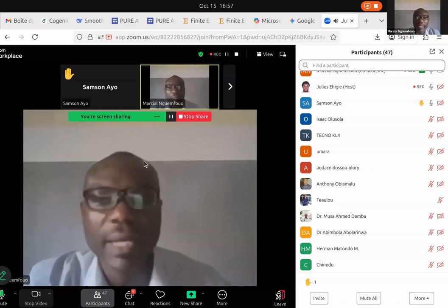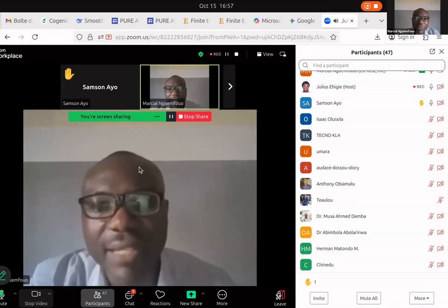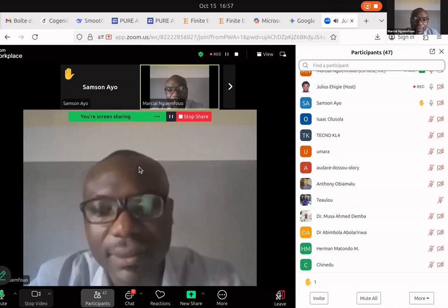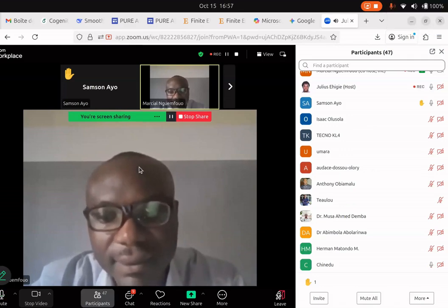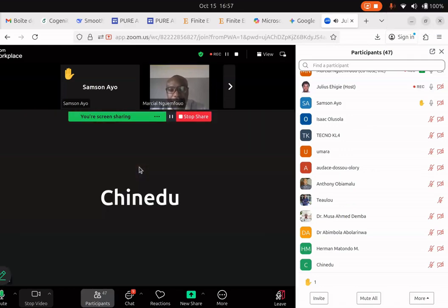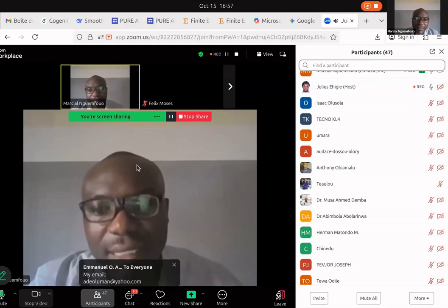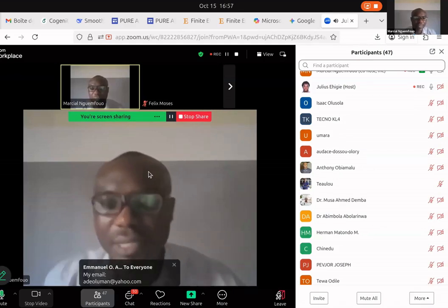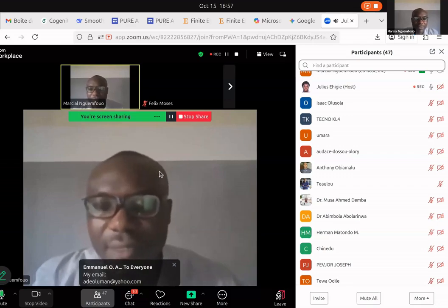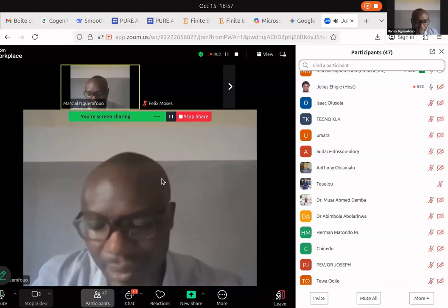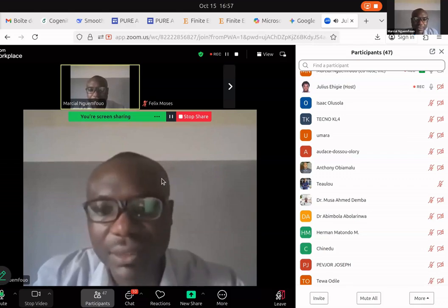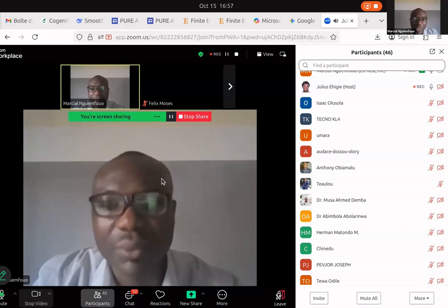In our case, the ILU preconditioner failed. To make the computation, I use a linear algebra technique to have the result here. Because when the matrix is not invertible, we have two methods. We can use the CG, conjugate gradient method, with some projection.